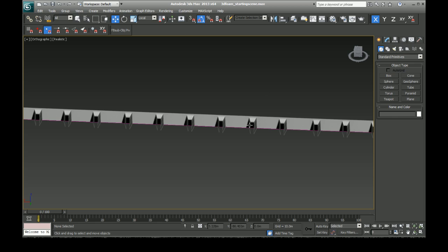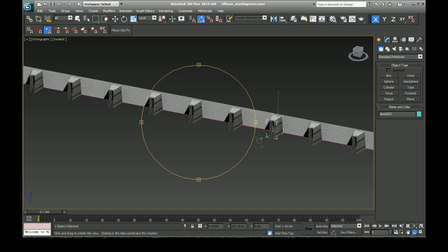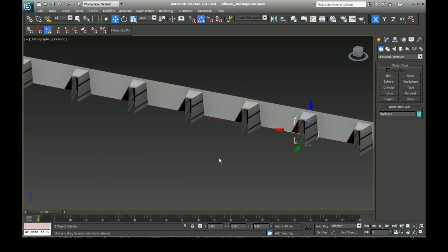You can also use snaps. I'll go over that here because I know I've done that in a previous video. You may be working in the center of the corner where your issue is. Turn off angle snap. I'll turn on that, I believe it is the snap to edge toggle. Now what I can do is take that block, and this works anywhere on that segment as well, in the corners or however you want to do it.